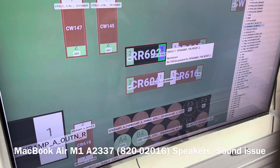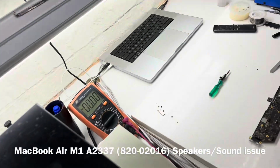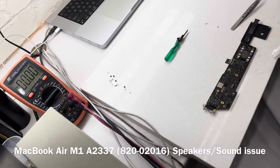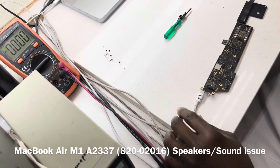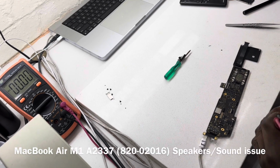Okay, so let us see what voltage we have here. We are supposed to have 1.8 volt. Now, if we have less than that, it would put our speakers into reset mode. While the speakers are in reset mode, we will not have the speakers being activated. So let's connect the charger to it, and let's see what we have on pin 11.